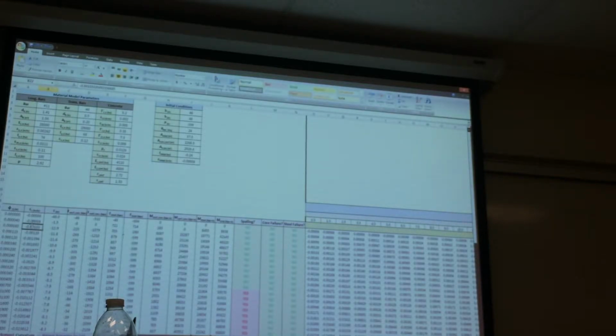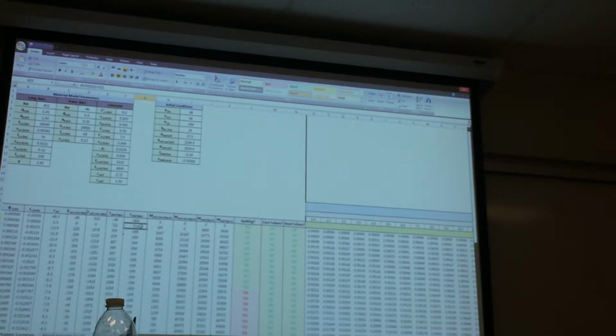But you'll see that if I use the step before as my first guess, and I look at the force on the cross-section now, this force here is not equal to the axial force on the cross-section, right? This is now equal to, let's say, 700 kips positive in tension. This should be equal to 600 kips compression. So you want to tell Excel, I want you to change this value of strain such that this cell is equal to the axial force.